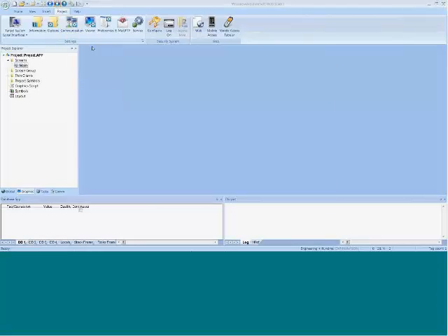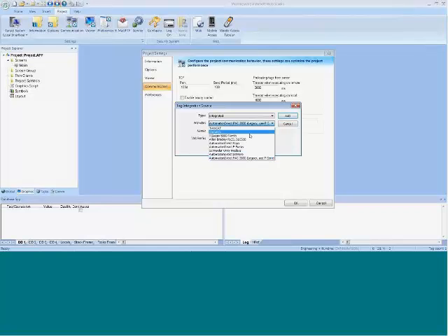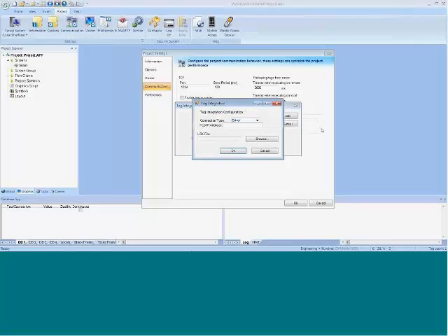I can go here under Project and Communication and set up a source for my tag integration. What this can use is different PLCs' export files or their tag databases or I/O databases, whether it be from Automation Direct, Schneider Unity Pro, some of the Allen Bradley devices, Codesys, or even TwinCAT. But if you're using RS Logix 5000, let's say, on a packaging machine, and wanted to call this my PLC, I can add that as a source, and now I can give this an IP address and point to the L5K file.